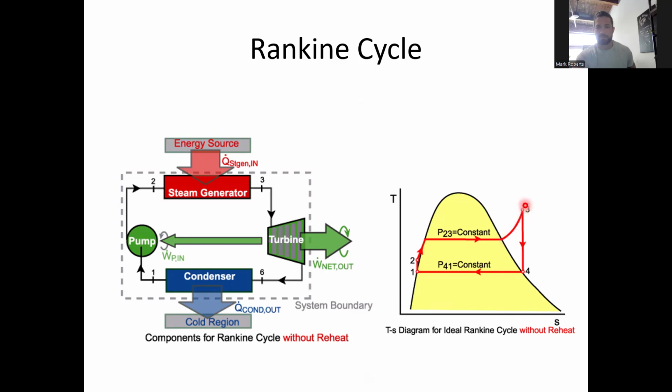make it superheated. So again, we start from subcooled, increase the temperature at constant pressure till we get saturated liquid, and then we vaporize all of the liquid at a constant temperature, constant pressure process until it's saturated vapor, and then it comes out as a superheated vapor coming out of here.